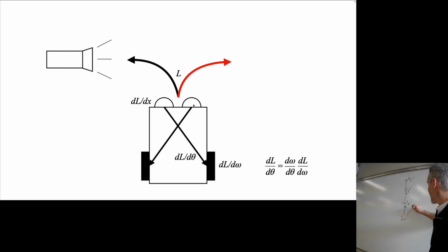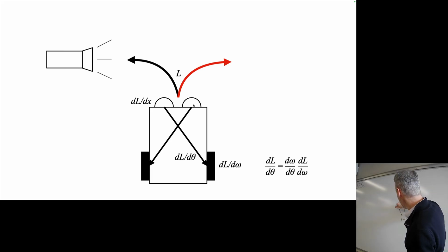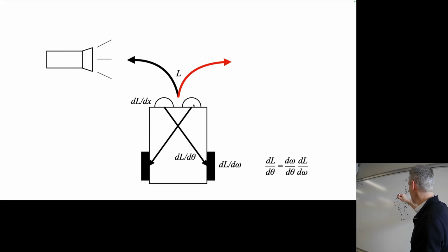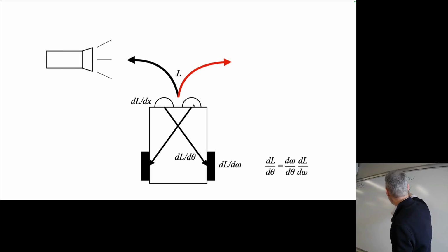So let's add that backward chain. From L, from loss, the differentiable simulator also is able to calculate the local gradient for the turning speed of the left wheel. Keep going back.